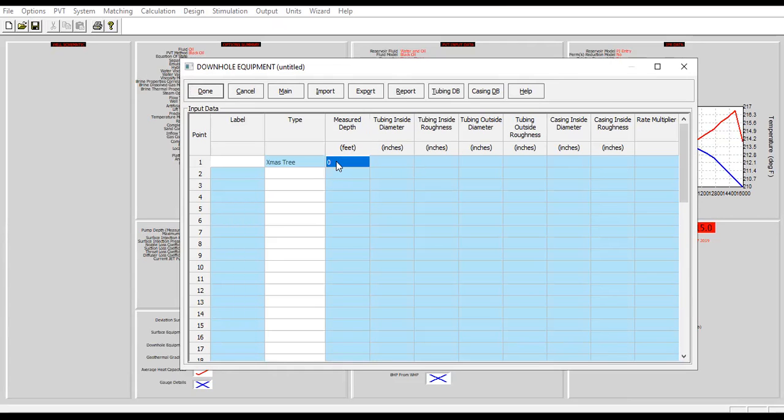This is an offshore well. The measured depth 600 feet. Then we have tubing. Open the drop-down menu. The bottom of the first tubing is 1000, inside diameter 4.052, default roughness, outside diameter 4.5, casing inside diameter 6.4. So from here, we can get the result for the annulus dimension, all right?